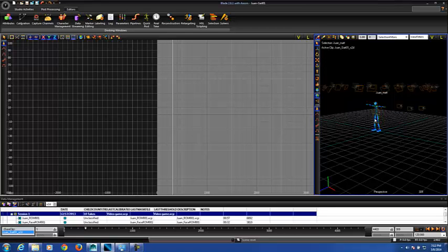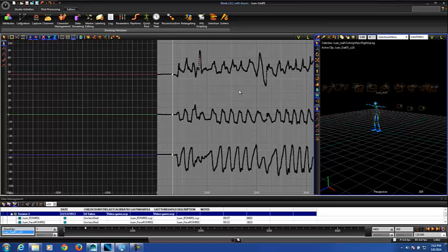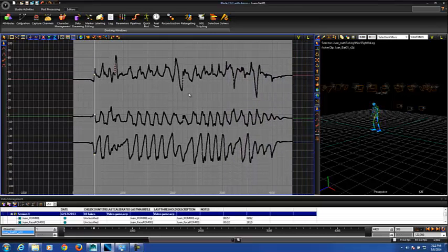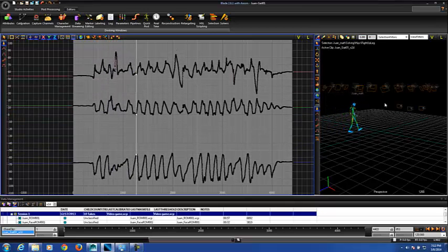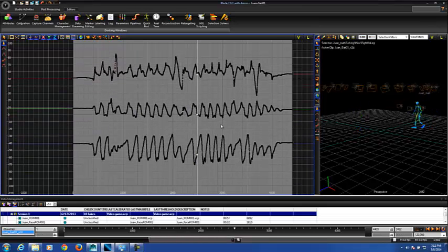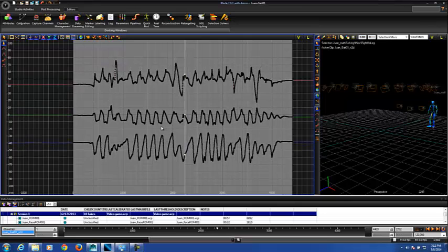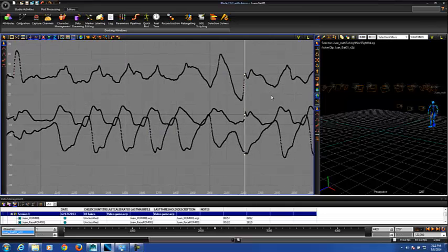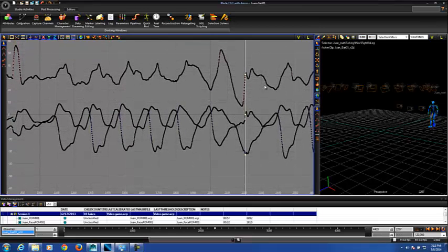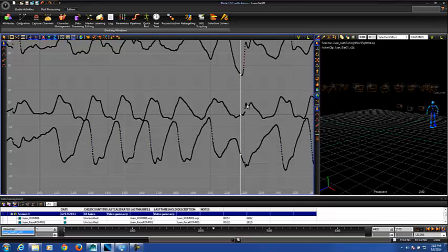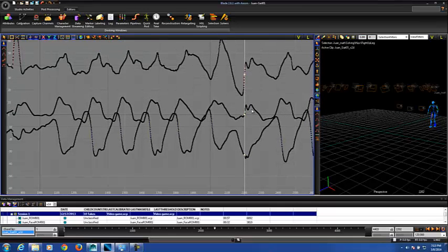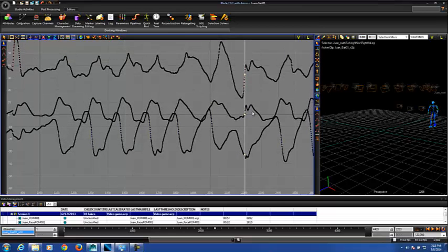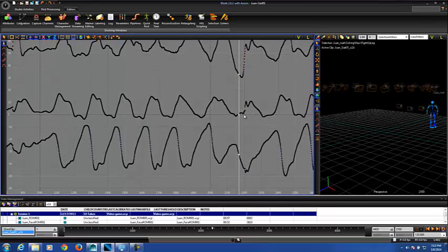Let's say we wanted to look at the right leg for this gait. That's basically the ground truth data the software generated. As you see, a little bit of the data is missing, and those pieces are these blue filled-in lines here. For example, when the student went out of the view of the camera, right around there, some of the data is missing. So I'm interpolating with a linear interpolation to fill in the missed data, which I think the system automatically does a really nice job of.